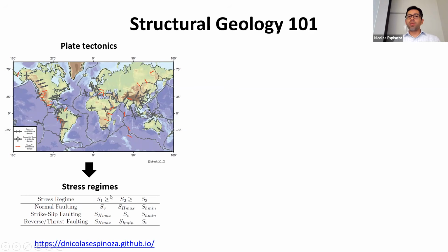We're going to have places which are called normal faulting regime or extensional regime, in which the least principal stress is horizontal. We might have other places, however, where plates converge, like for example here or over here, usually associated with big mountains, where the plates are converging and there is a very high horizontal stress. Sometimes the two horizontal stresses are larger than the vertical stress. And as we're going to see later on, that's super important also for geothermal energy.